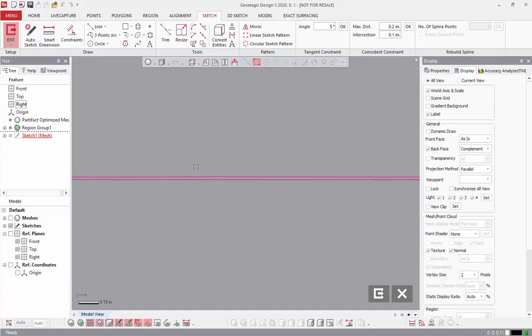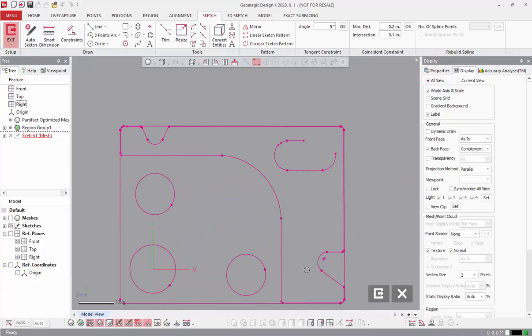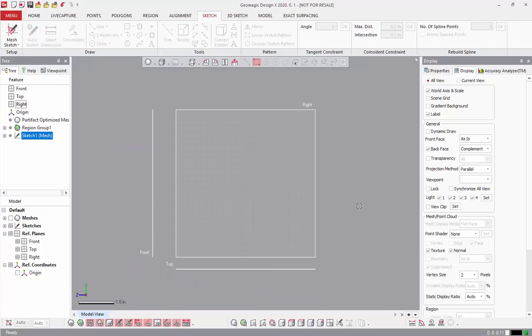This indicates to me that this part has a small amount of draft angle to it, where these walls are not vertical, or at least perpendicular to the cross section. They have a small amount of an angle to it. If that is of some concern or some interest to me, maybe I want to investigate that a little bit further. So what we can do here is if I hit OK, the sketch will save, even if I didn't convert any of those polylines to actual sketch elements.